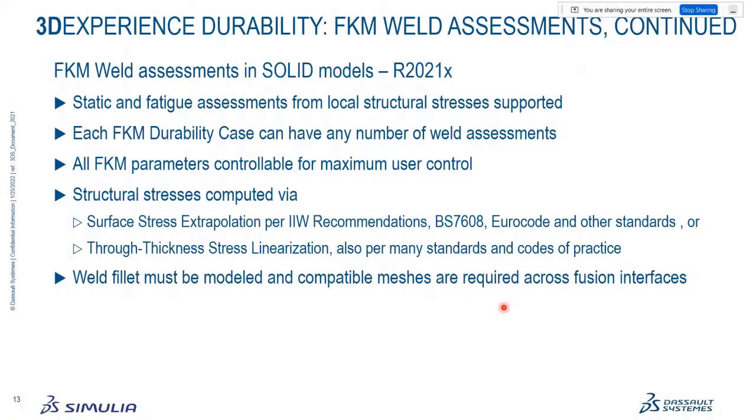The way the structural stresses are computed, we use surface stress extrapolation using the IIW recommendations. These are the same basic recommendations that are in British Standard and Eurocode and several other standards. Or sometimes the welds are too close together and you don't have enough distance to do surface stress extrapolation. So we offer an option to use through thickness stress linearization, also per many standards and codes of practice, right?